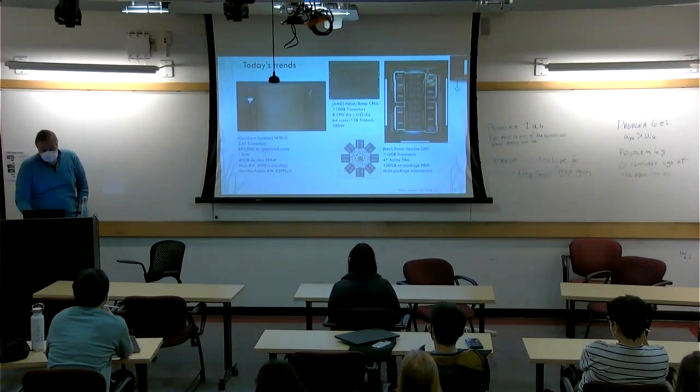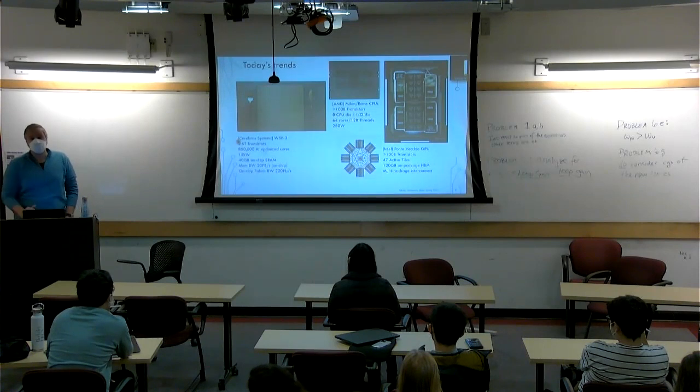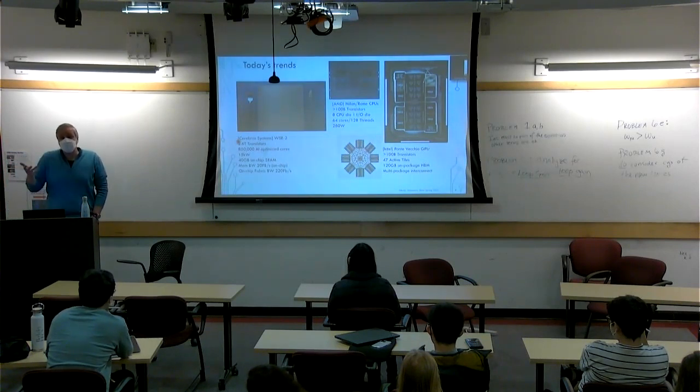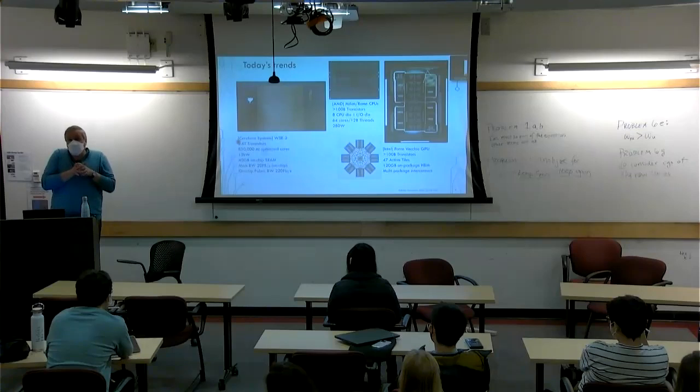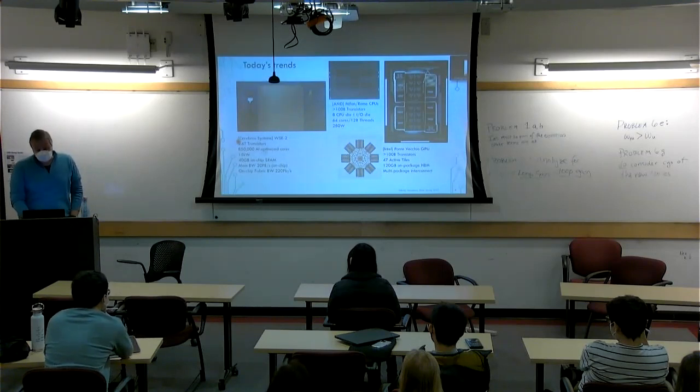If you look at it, it's 2.6 trillion transistors and 850,000, let's call them AI cores, right? These are not really your general purpose cores. These are basically matrix vector optimized cores, but smaller ones, I would say. They're not the size of the typical general purpose core, not even, I would say, the Rocket core.